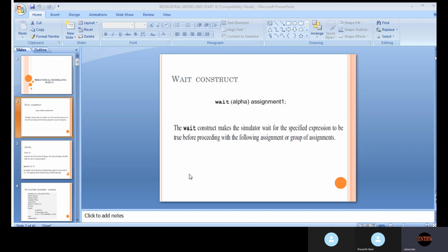Even Ganesh, if you have any doubt you can ask me. When you instantiate at gate level, if you instantiate a vector, an error will definitely come. You need to use like a of 8, c of 8, comma b of 8, a of 8. Yes.